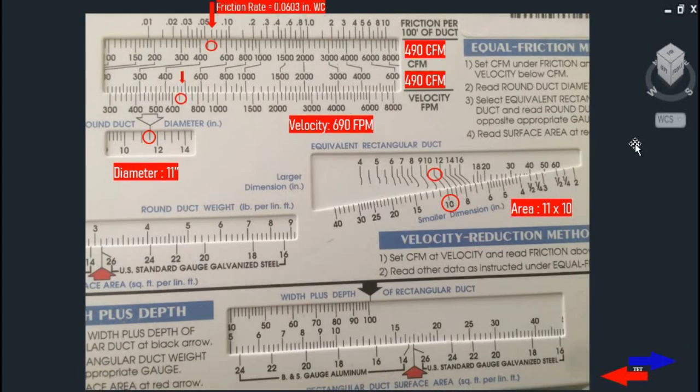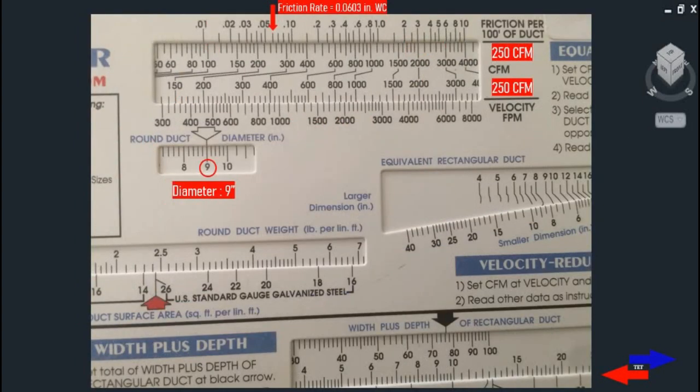And the last one for the supply duct at a friction rate of 0.06, we have a round duct diameter of 11.5 inches with an air velocity of 690 feet per minute with an equivalent rectangular duct of 11 by 10 inches.